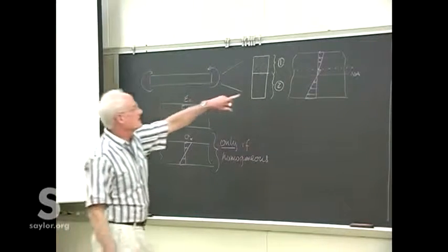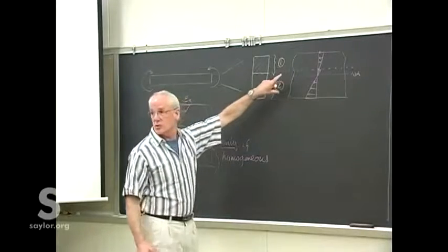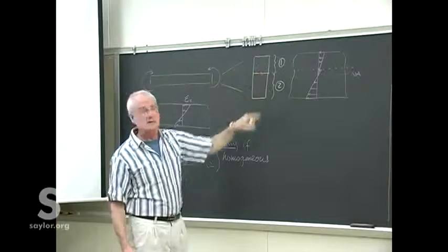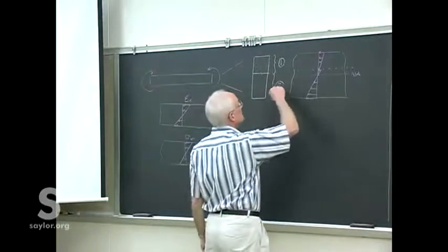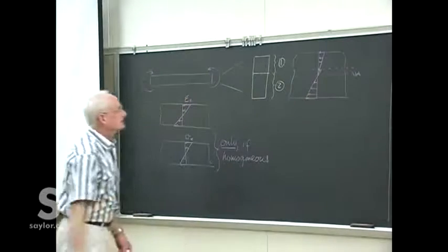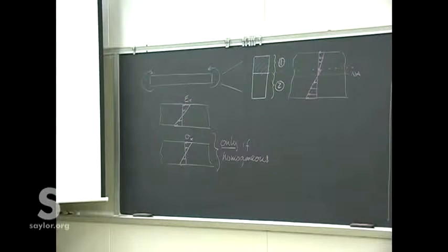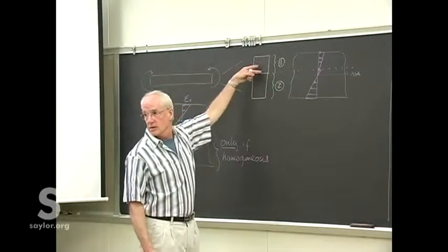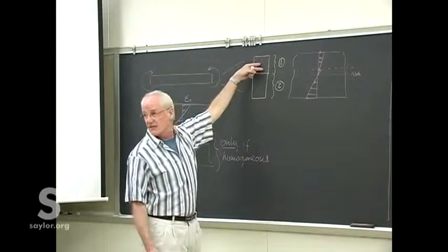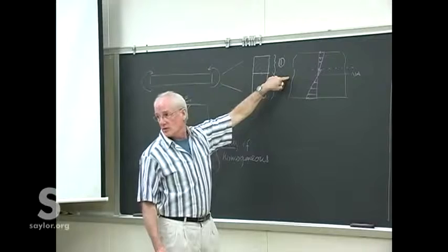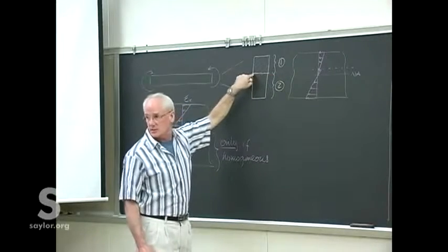This little sketch is assuming that E2 is greater than E1. If E2 is less than E1, then the stress distribution at the top would be greater. However, we can't just calculate that by applying the different Young's modulus, because the trouble is we don't know where the neutral axis is for this distribution.